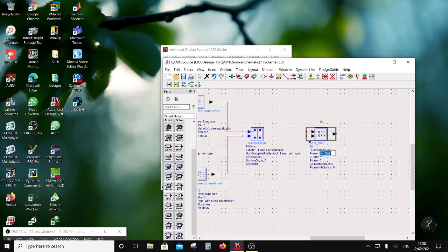correct? And okay, so this is a dBm, so you have to do dBm to watt of something, right? And then because it's an I and Q, I have to do a minus square root of 2, right? Reference is 1, gain imbalance, phase imbalance is 0, right? So fine. So now this I'm going to give to here, and this I'm going to give to here. So once this is done, I would have to do the output. So there will be a P out.